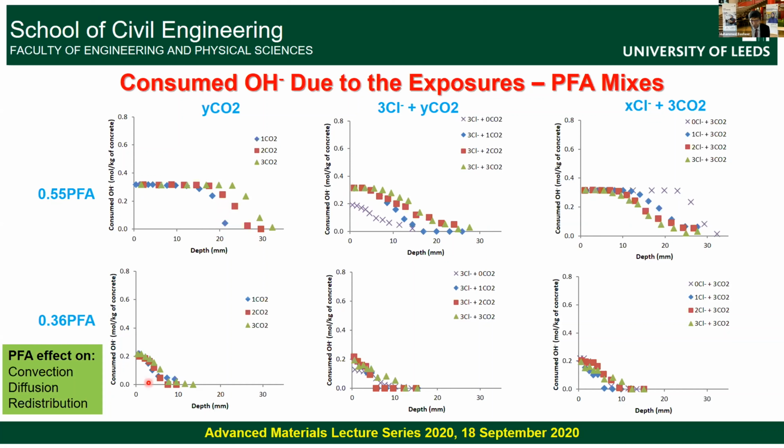And again, if you look here, there is not much of a difference. That means the model which we use here possibly should be sufficient for predicting here as well. So in good quality concrete, high performance concrete, this combination effect is minimum. However, in most of the concretes we use in structures, there is a need to consider the combinations of the